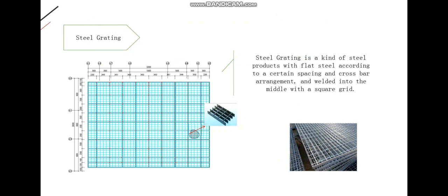According to the drawing, the size range of each cell plate is length 2200 mm to 3450 mm, width 675 mm to 866 mm. When it comes to a column, it needs to open a hole and seal it with flat steel of the same specification. The edge is 10 mm away from the column. The position must be laid according to the elevation and the number specified in the drawing, to the right seat with accurate positioning, and make sure the clearance is 10 mm.